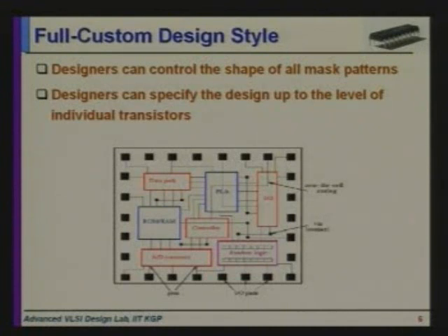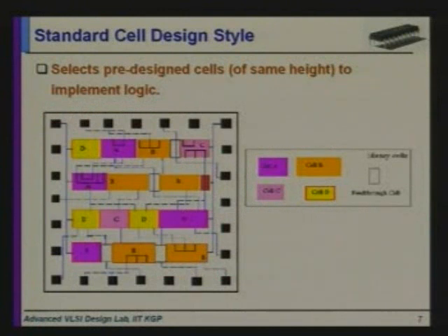right? But in the case of an ASIC, say, which will be planted in a toy, we need not make such complex performance optimizations in terms of area, power, etc., right? So there we can say that standard cell design satisfies this, where I have a library of cells which is prefabricated and pre-designed.